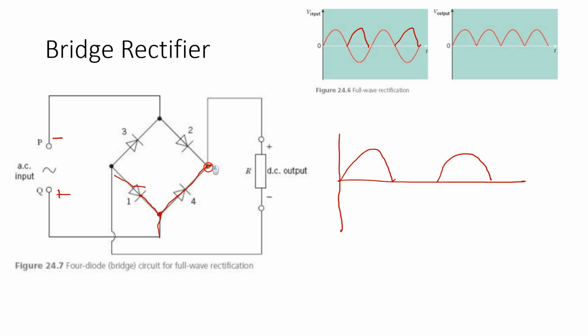When it reaches this point, it's now looking to see, can I flow through number 2? No, it won't flow through number 2 because it's a positive signal and our positive voltage. So it's going to allow this to be in reverse bias, which is essentially an open switch. Then it continues now to the diode, right?